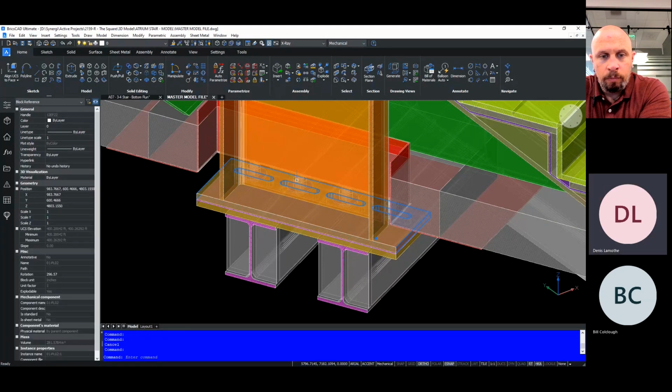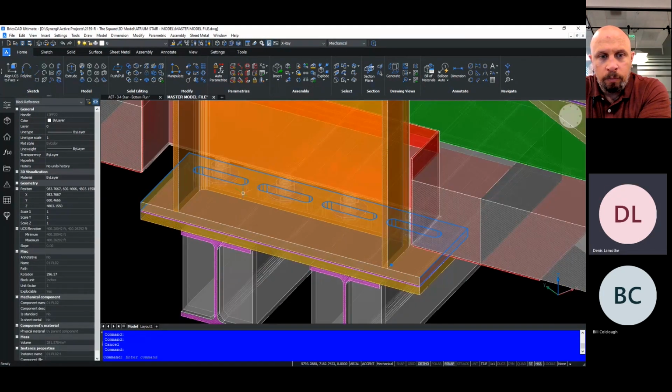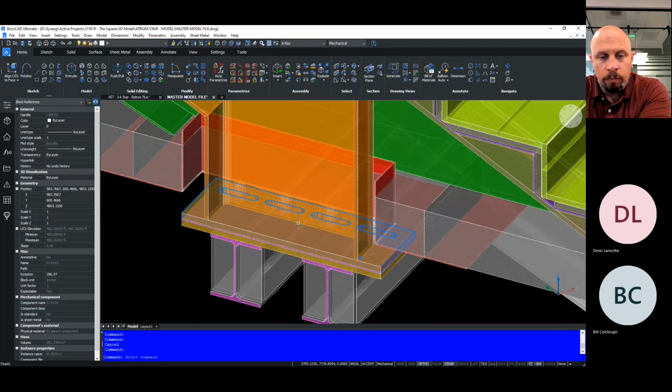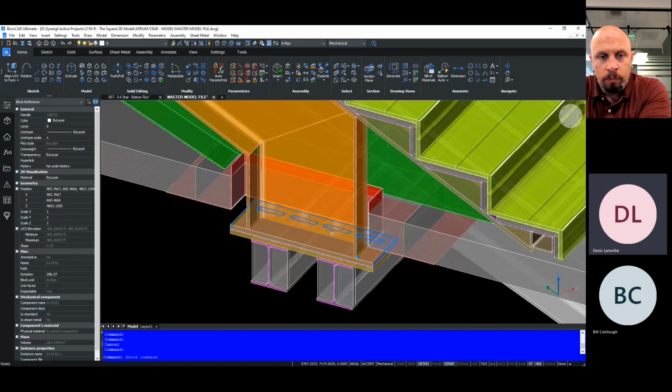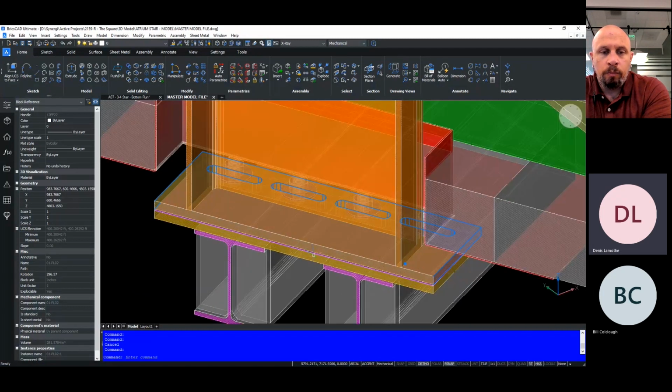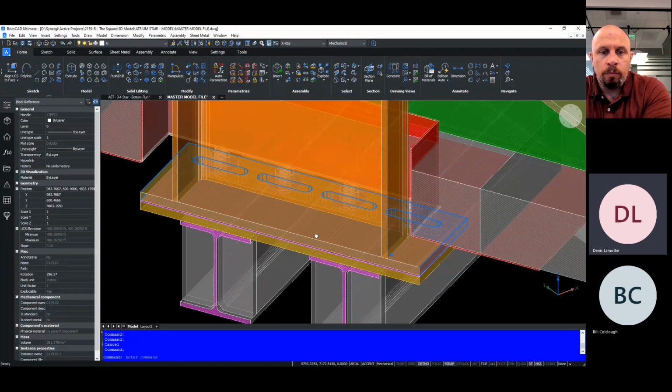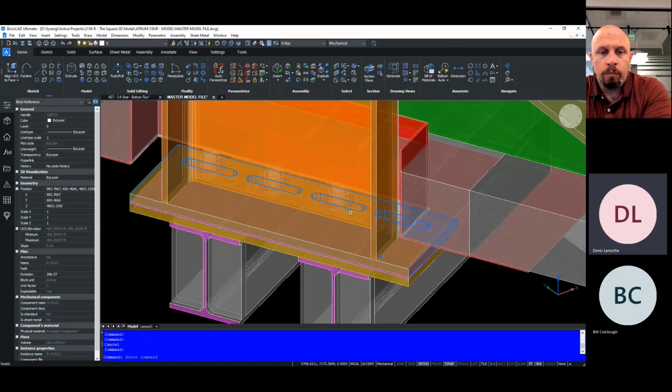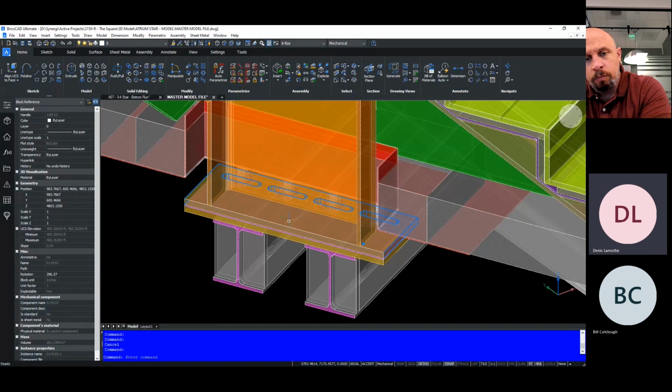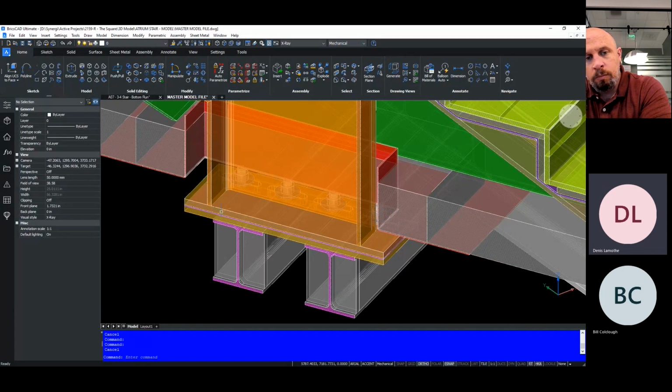And the base plate here, you can see it's got slotted holes, which would allow for some movement side to side, or actually front to back. These slotted holes are a little oversized here because this project was on the West Coast, and with the earthquake and seismic activity there, the requirements for that slip connection are greater than anything you would see on the East Coast. On the East Coast, you would rarely, if ever, see slotted holes drawn to this extent in any of the base plates or even the plates at the top.